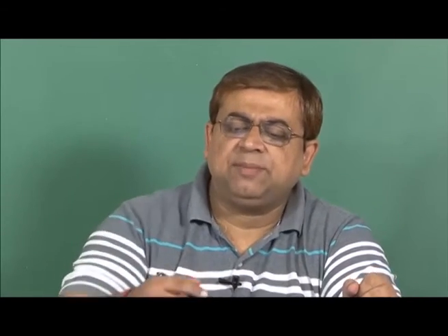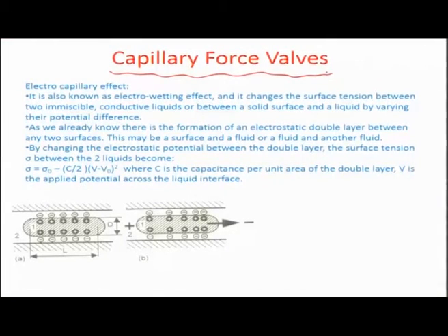And one of the reasons why electrochemical may be showing better efficiency is that if we compare the internal energies in the case of formulation of a bubble thermally and electrochemically, they were very different in nature, and so that gets expressed into the final efficiency equation. So, we will now go ahead and look at some other schemes for doing actuation. There are, for example, capillary force valves, which are again actuated through